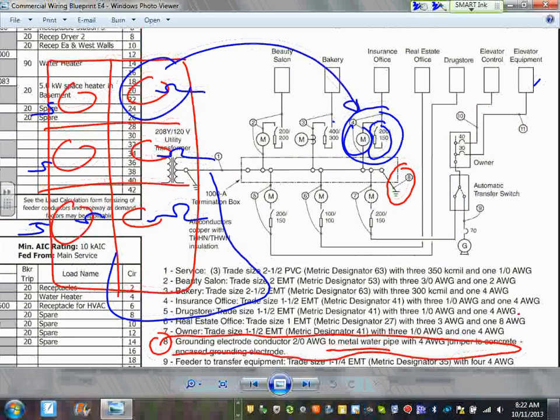So two options: either a gutter where I can tap a meter socket and a fuse disconnect, three separate boxes wired together, or one big box bussed together, and all I have to do is tap into the feeder from each one of them. This will be a better design here, right? All controlled in one location and so forth. What are the disadvantages? The equipment is a little bit more expensive.